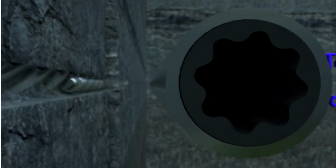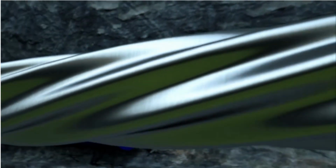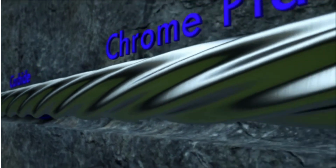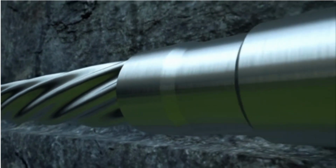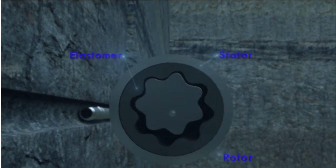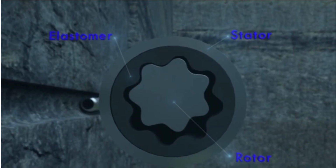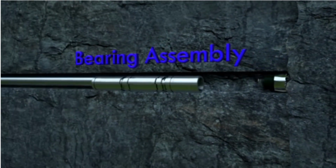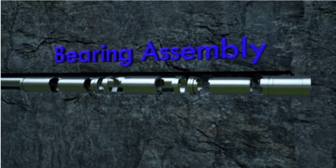The bonded stator and elastomer are combined with a highly polished rotor, with one less lobe than the stator. Dynadrill rotors are made out of stainless steel and can be carbide coated or chrome plated to maximize protection against wear and erosion. The stator, elastomer, and rotor work together in unison to create a spiral motion that minimizes friction and improves efficiency.